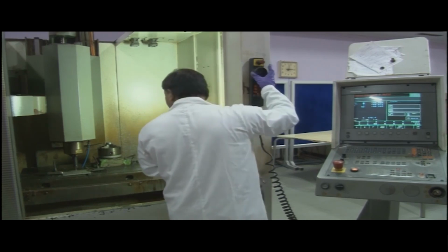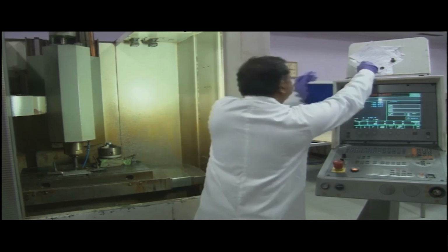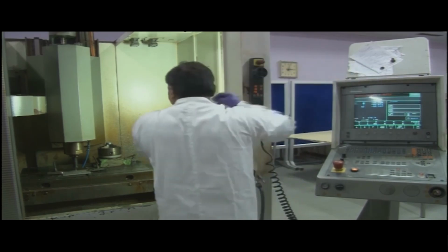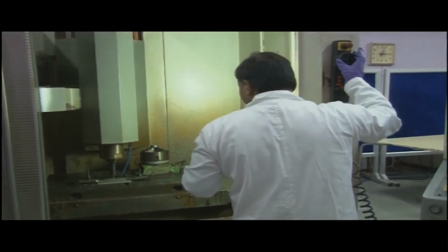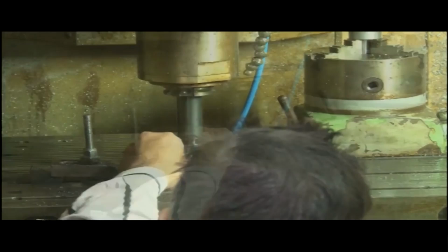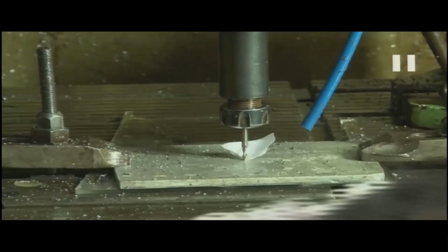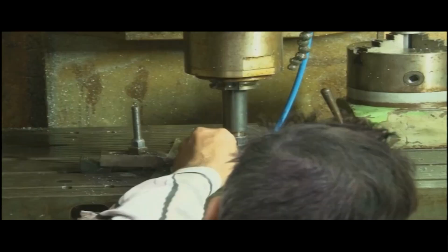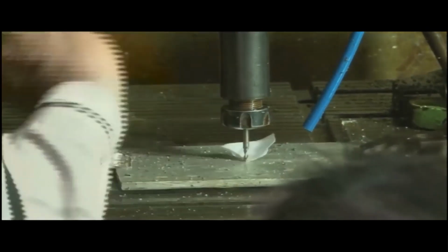So, for Z also, and for x and y, we have to bring it closer. How do we do that? One of the ways is we put a piece of paper between the tool and the workpiece. Slowly we start bringing our tool down. See, this paper is being rubbed below this, it is stuck. Let us repeat this. The paper is being moved, once it is stuck, it is moved.